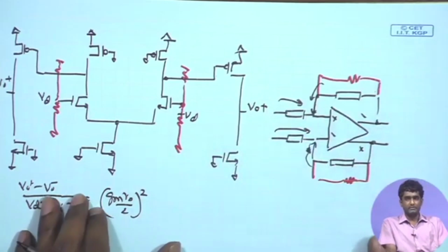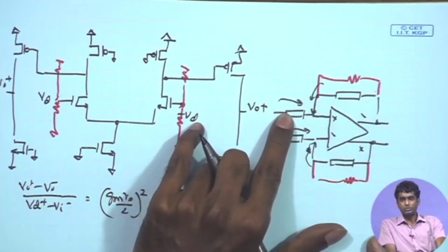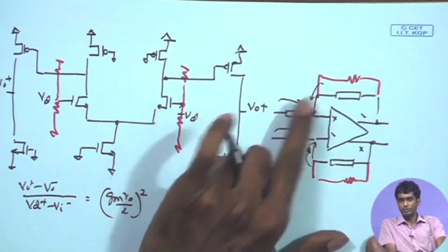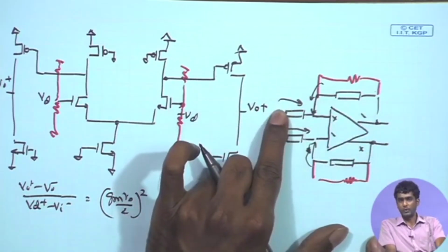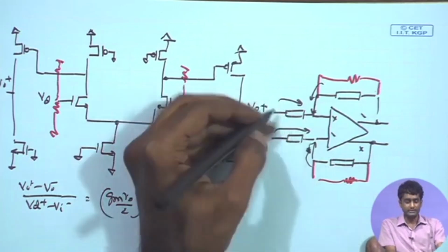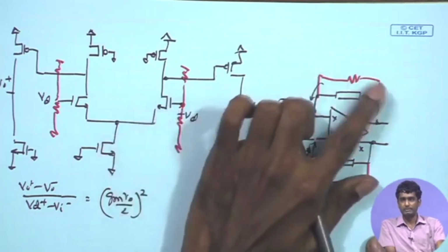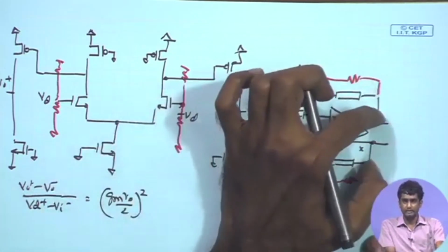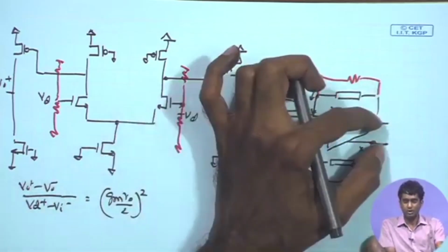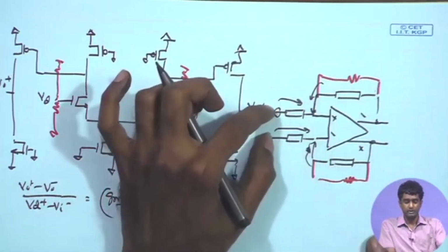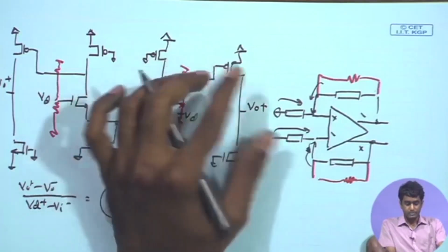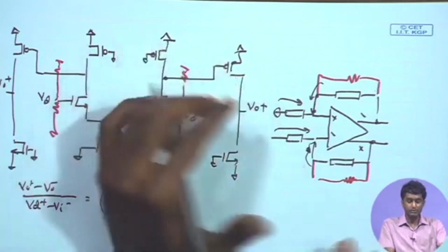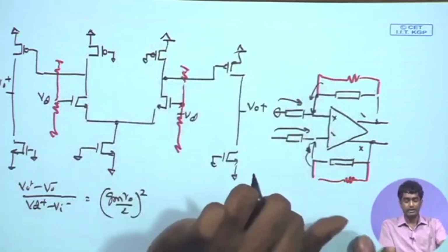So in the very beginning, we have said that we don't want to use resistive feedback, R1 and R2. One of the main reasons is that it can lead to a lot of noise, because whatever noise is being contributed by R1 will get amplified by the amplifier, and it can increase the overall output noise of the amplifier, and the equivalent input referred noise, as a result, will be bad. So, that was the starting point for why we chose the capacitive feedback.